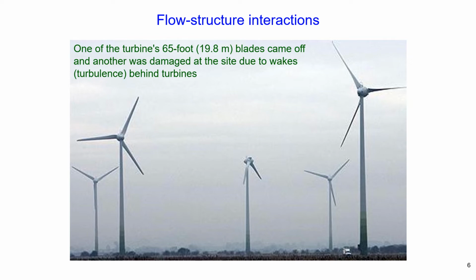As you know, turbulence intensity affects the generated wakes. So you need to be able to calculate turbulence intensity and also take this into account in your design process. Let's see how flow and structure interact with each other. Assume we have tidal current flow from left to right, and the flow is approaching a tidal current turbine.